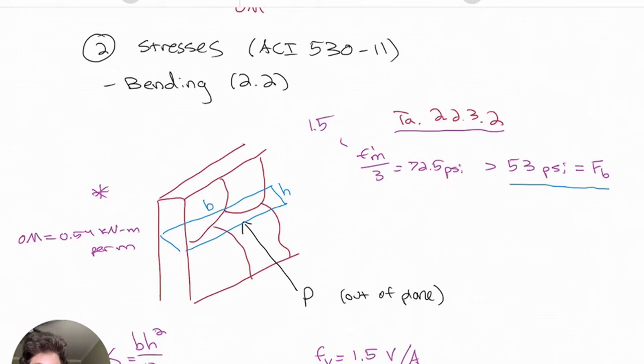And the section is illustrated here where B is the shortest wall length from the anchor to the foundation, but we'll just take this as 1 meter. Remember, because we're doing this per 1 meter of wall, and H is actually the actual width of the wall, so that is 30 centimeters in our worst case scenario analysis.